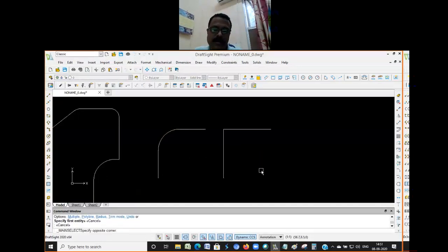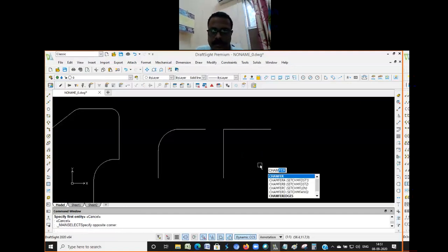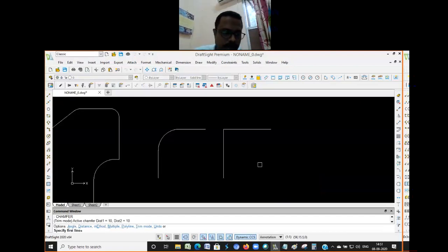For that, I use chamfer. Okay. So it says many things. I just check the distance. What letter should I type here in order to check the distance? Options are there: angle, distance, method, multiple. So type capital D, it will give you the distance.